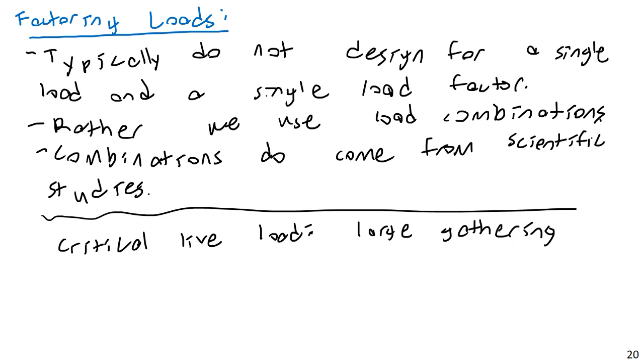So again, that might be a critical live load case, because in that case, maybe that classroom is absolutely stuffed to the gills. Maybe we're going to completely ignore fire code and just shove 100 people into a classroom that normally seats 20 or 30. Maybe we'll shove 200 people in there. And so we get an absolutely ridiculous live load. That might be your critical live load case.